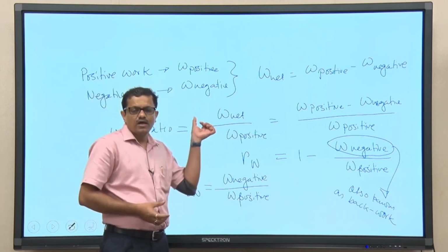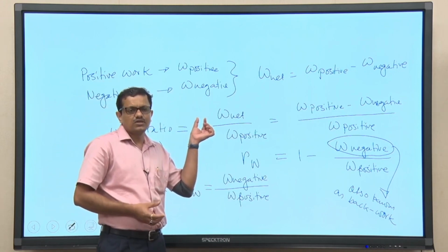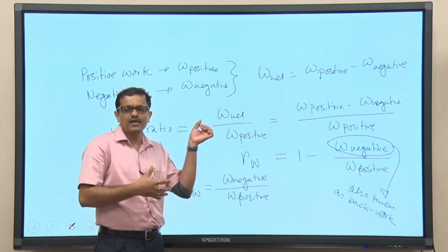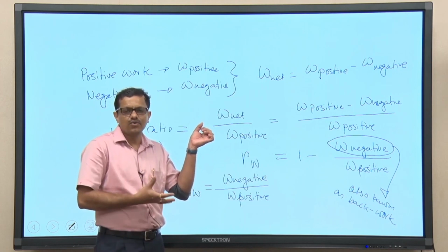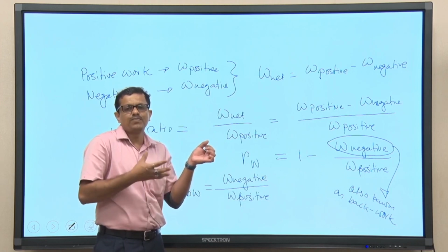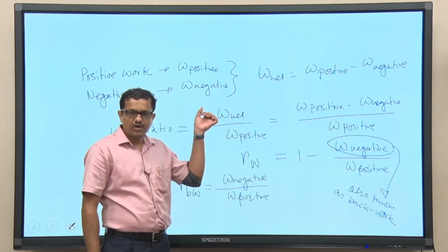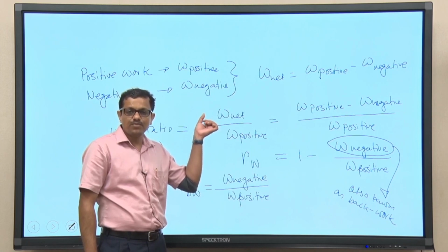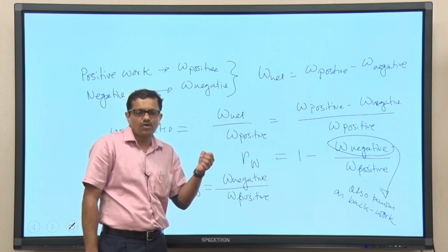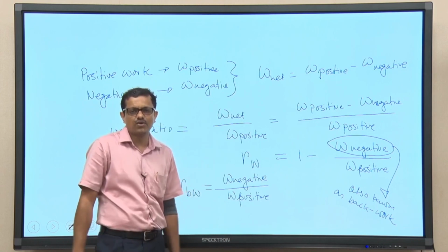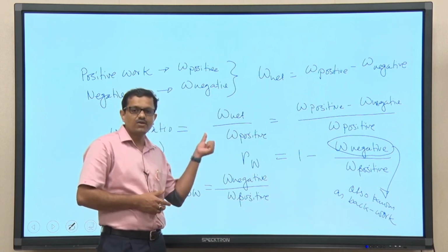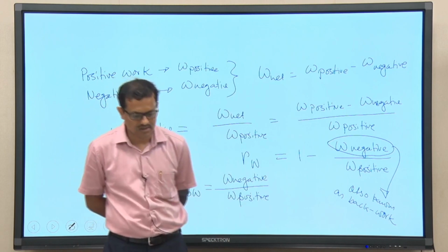We shall be discussing the analysis of this Carnot cycle in the next class, but before that we have discussed a few issues related to the performance of the power plant. When we are trying to compare the performance of different actual cycles, what should be the basis of the comparison, rather what would be the performance measuring parameters. To this end, we have discussed one important index, that is specific steam consumption, which is also related to W net, that is the net work. Also we have discussed what we mean by net work. From there we have defined the work ratio and back work ratio.